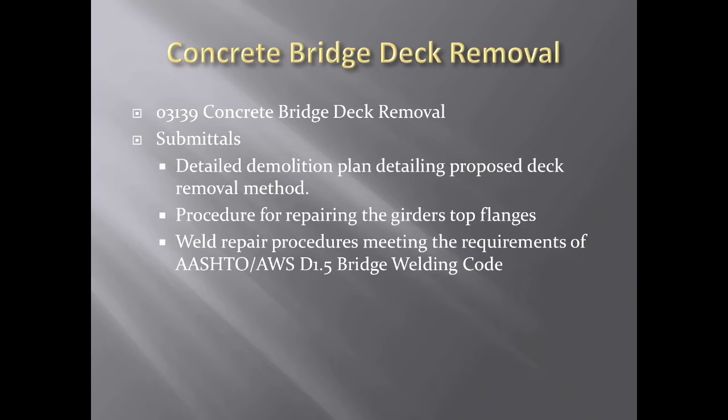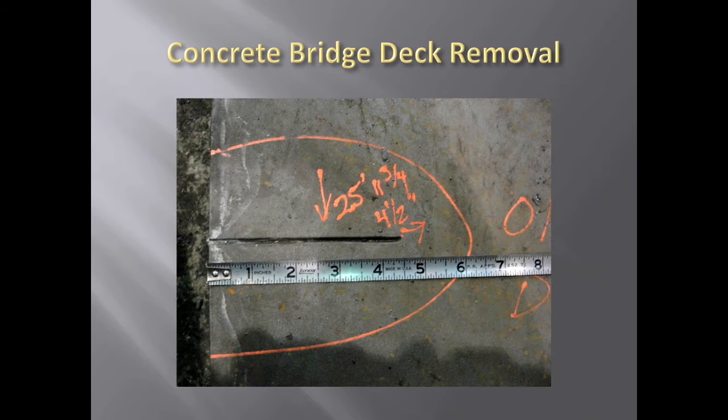Deck removal on steel bridges. Concrete, we don't really deal with the concrete removal on concrete girders, but we do on the steel. Some of the things they need to turn in is a removal process procedure, to make sure that once they've got everything under control, all their procedures are turned in and bought off by the engineer of record. And it also requires welding procedures and repair procedures in that.